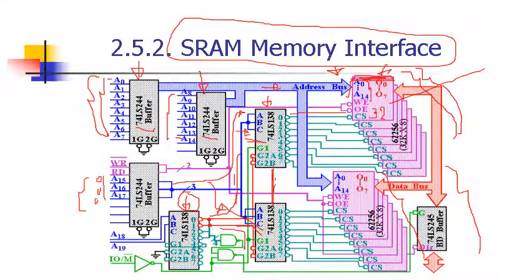Okay, good. So again, we have to interface 16 different chips to our system. We arrange these 16 into 2 groups of 8, upper 8 and lower 8. We use 2 decoders to access any of these upper or lower 8s.